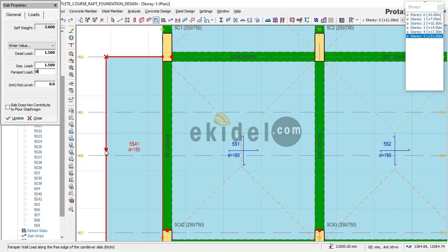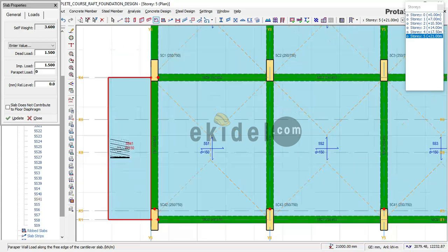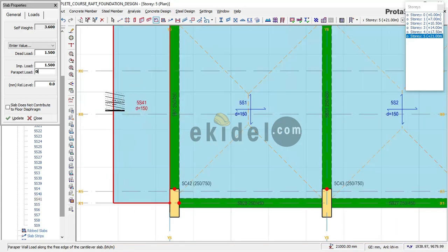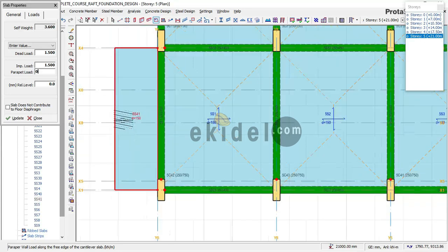You see that this load, this point now will go off. I can see that this stuff that was showing here as if an X and an arrow here and also an X here has now gone off. That means that this cantilever slab is just a fancy slab. There is no load on it, which is very, very bad. So you must load your cantilever slab.